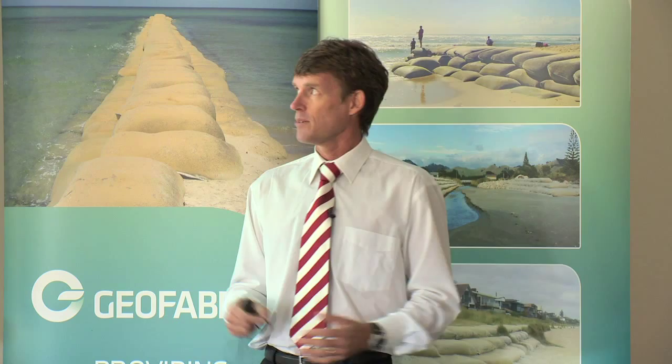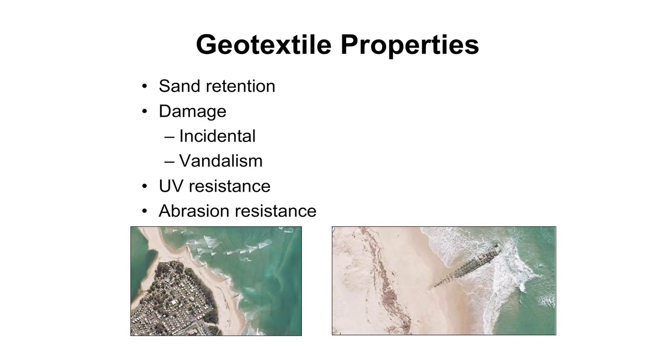Okay, from the geotextile properties point of view, there's a number of factors that we have to take into account when we're designing with these structures. The sand retention, the type of damage that you'd be expecting on site, whether it be incidental damage from driftwood or boats, or vandalism, UV resistance and abrasion resistance. I'll go into a bit of detail on each one of those areas now.